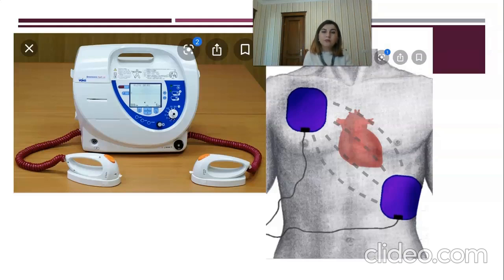If we compare 1 milliampere with 10 milliamperes, 1 milliampere is more dangerous than 10 milliamperes. What causes this? If we send 1 milliampere, it will tetanize only part of our body, and desynchronization of the other muscles will occur, because only one part is affected by this current.